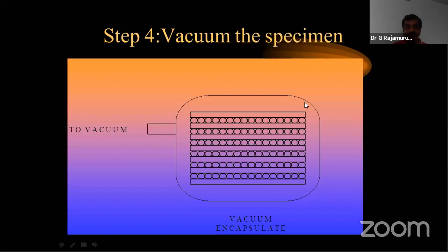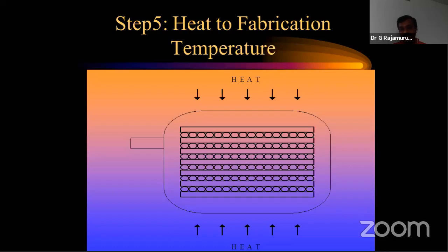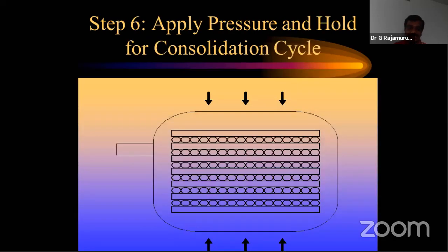And the fabrication, how are they doing this fabrication? The fabrication is done by the vacuum compression technique. Okay, because there I don't want any interruption. I don't want to produce air bubbles in between the aluminum foil and the matrix. So that will reduce the strength of the composite material. So in order to avoid that particular problem, most of them do it in a vacuum chamber, right? So by using heat and vacuum, they finally get the structure.